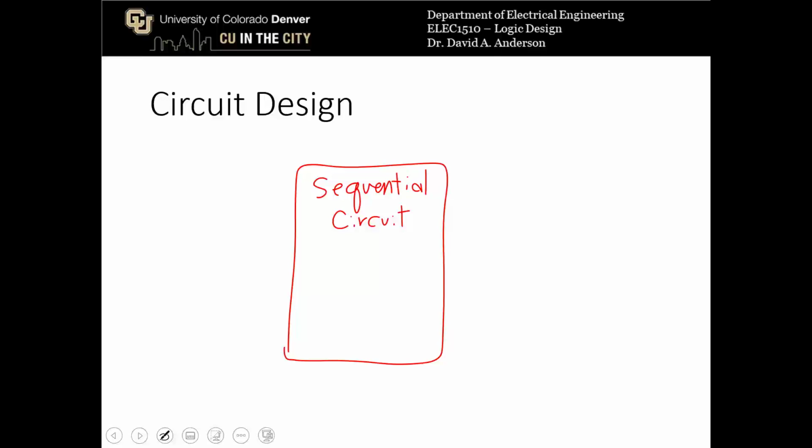But basically, as the input to the sequential circuit, I have X. As the output from the sequential circuit, I have the 2 state variables, S1 and S0. And now the actual output that I want is F, where F is S1 and S0. So now I just have an extra output that's formed as a combinational circuit of the two output state variables.